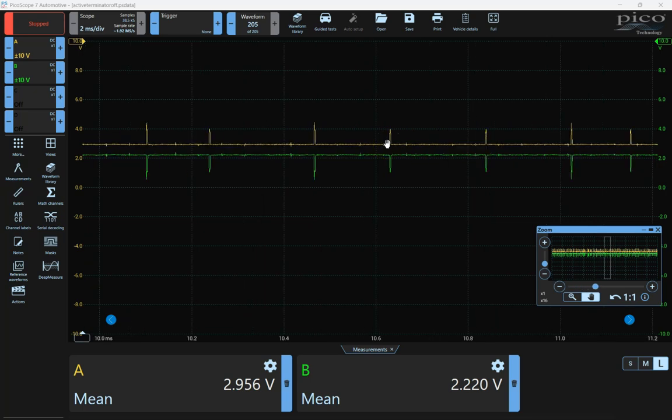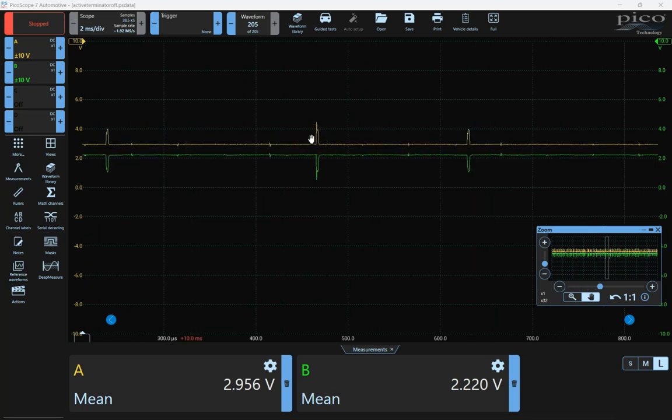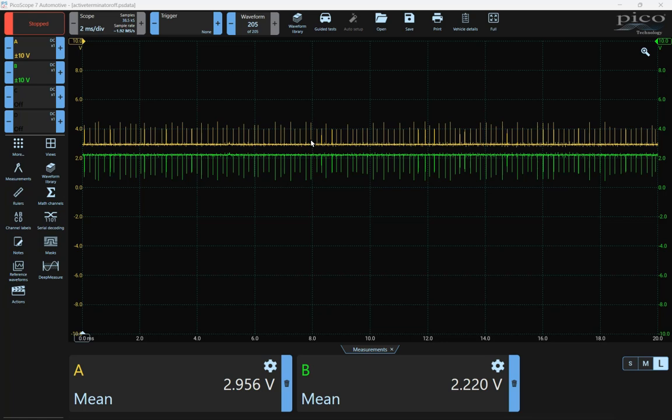We can see that no communication is possible. The reason we have the voltages at this level, as I said once again, is that there are electronics within that terminating bias circuit, and they're apparently pulling it to this level. If I were to then go to that active terminator connector and I jumpered from terminal A to terminal B